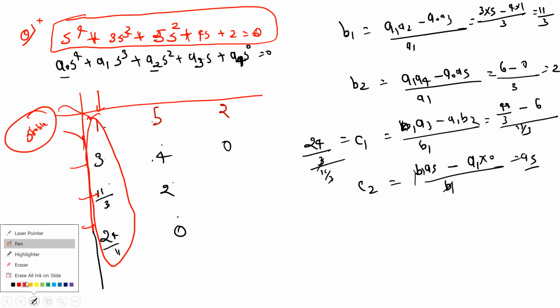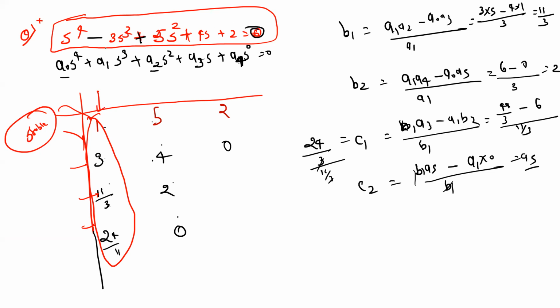But if, in place of positive, the sign would be negative, while observing the characteristic equation only, you can see there is a negative sign, then the system is unstable directly. But if it is positive, then the system may be stable, may not be stable. So we have to make the Routh array, and after that we can solve this particular thing, right? I hope this thing is clear to all of you. Anyone has any doubt?